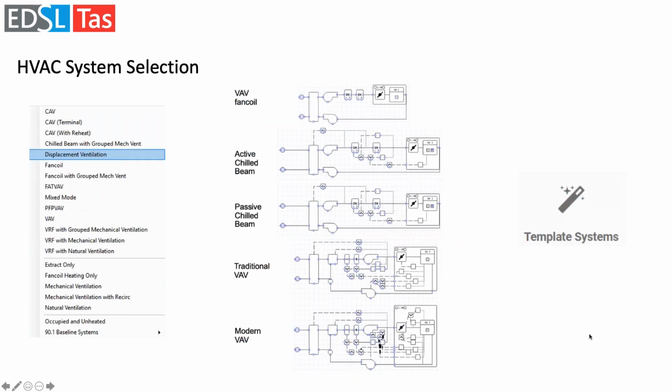The next part in this modeling cycle focuses on templatized HVAC system selection. So you're not really drilling down into all the setup of those. You're using typical setups, but you're maybe changing out different types of systems to analyze. There's a bunch of templates and tasks that you can pick from, shown on the left, and all of the baseline systems from 90.1. The idea is you just pick the type of system, apply it to a certain subset of thermal zones in your model, then run it, see how it performs, and compare that to other systems analyzed.